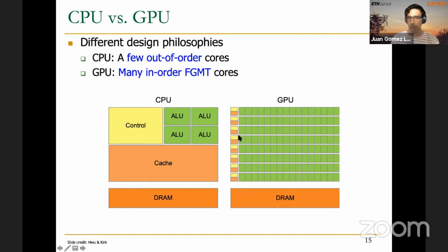What they have is a lot of small compute units, all these SIMD engines and SIMD lanes that we have discussed in the previous slide. However, they are much simpler. These cores are usually in-order cores, so they don't need as much control logic as out-of-order CPU cores, and caches are pretty small as well, as you will see.